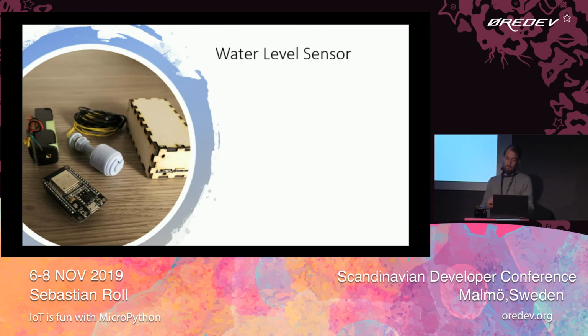So I had a microcontroller, I had a battery pack, and of course I buy things online that I don't need sometimes. So I had this binary sensor, which is almost like a balloon on a rod, and when you put it down in water, the balloon goes up, it floats. So it emits a signal of 0, for example. And when the water level goes below this sensor, the balloon goes down, and there's a magnet inside, so it knows which state it's in. So then it changes state. It's a binary sensor, from 0 to 1.